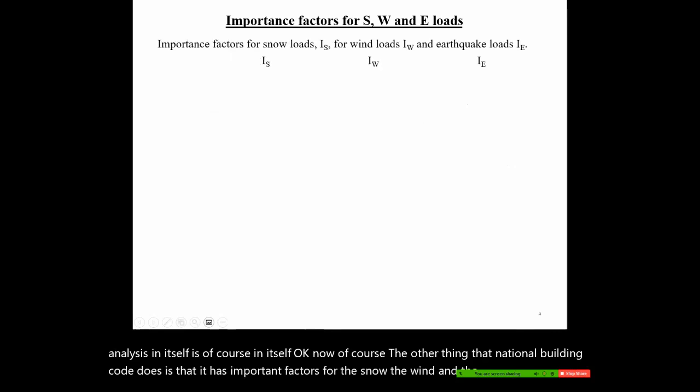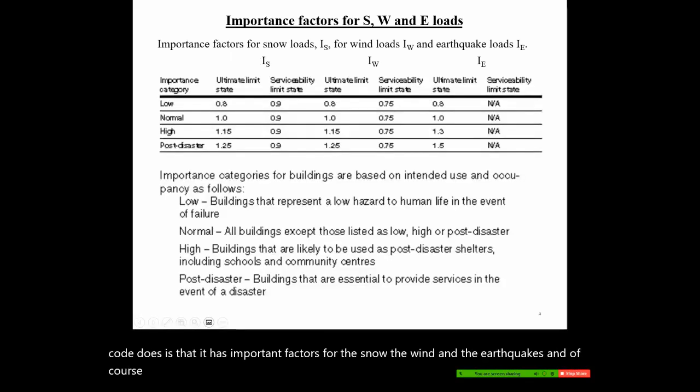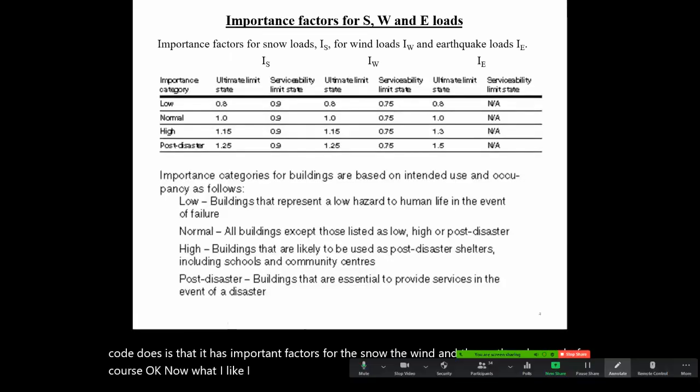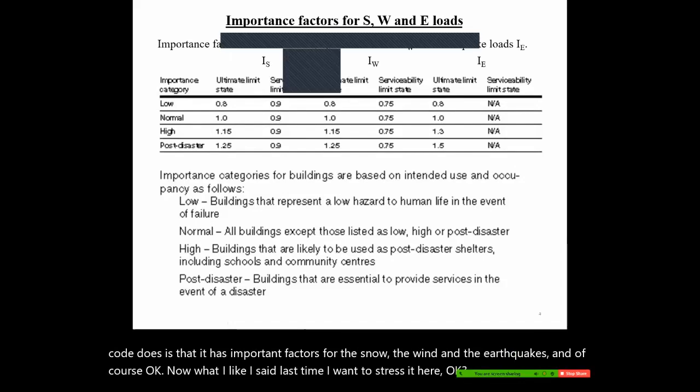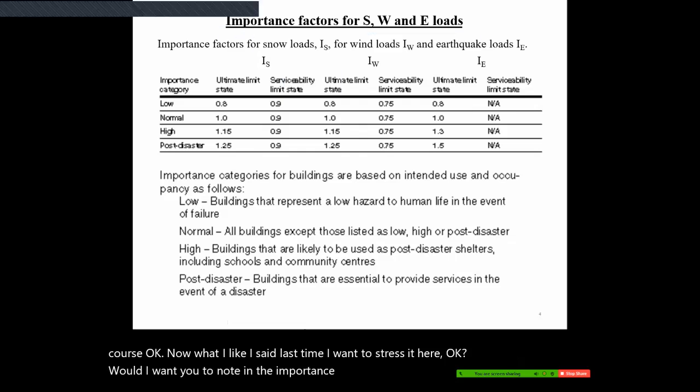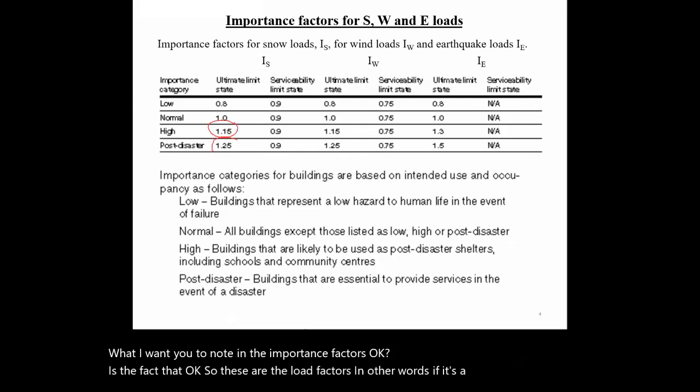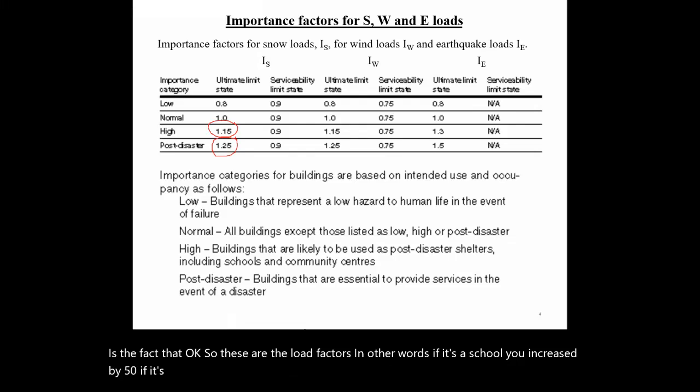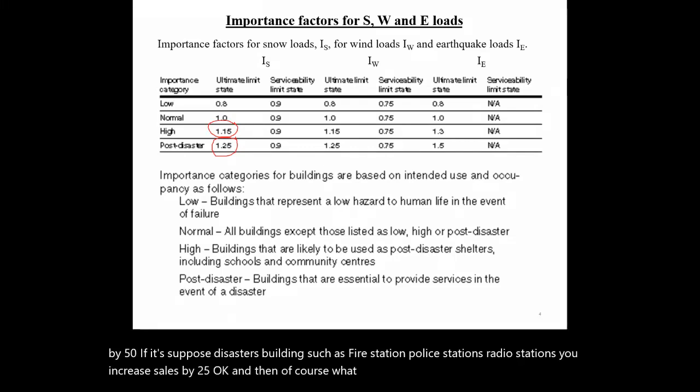And of course, like I said last time, and I want to stress it here, what I want you to note in the importance factors is the fact that these are the load factors. In other words, if it's a school, you increase it by 15%. If it's a post-disaster building, such as fire stations, police stations, radio stations, you increase those by 25%. And then, of course, what you have to keep in mind is that this is for strength.